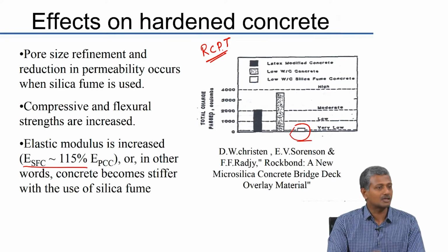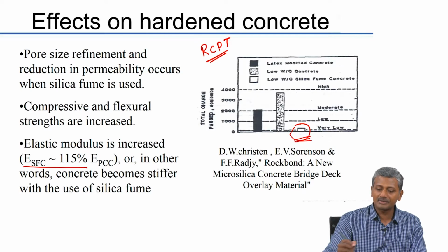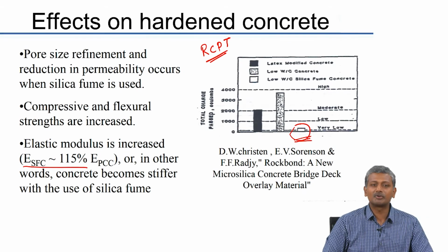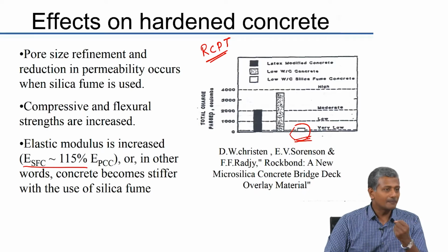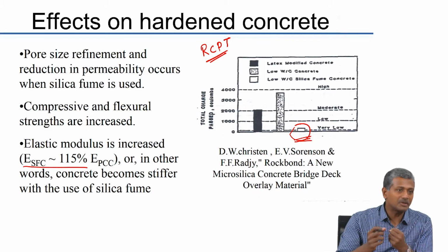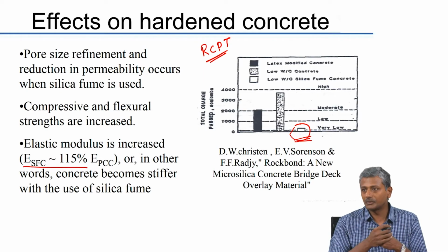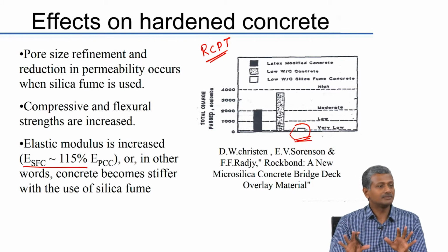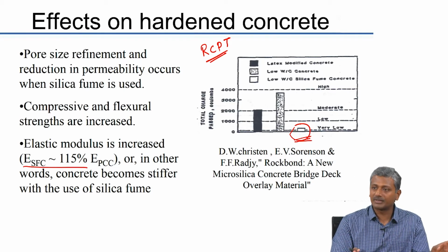So when you test a concrete with silica fume, it is no surprise that you are actually getting a result that is extremely good. Now of course we are using the same result to also propagate the concept of limestone calcined clay cement. Same thing is happening there also. Okay. Even in that case, your alkalis or the conductive part of your cement is simply getting captured by your mineral additive, right. That is the glassy nature of the mineral additive, simply trapping these alkalis and preventing them from moving around. Okay. So when you do not let your charges move around in the concrete, you are not able to pass that much current through the concrete, and as a result the charge passed in this test becomes quite low.